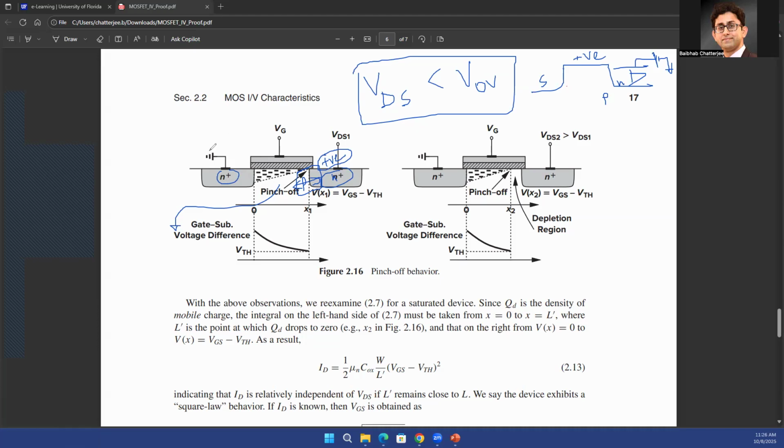That's a great point, that why does it have n plus in this diagram, and in the slides it has n. In terms of the physics, nothing changes, right? You still have electrons going from source to drain, the basic fundamental physics, nothing changes. The value of the current, the number of electrons that you can source, the number of electrons that are present in the drain, all of those things change, right? If you heavily dope it. And again, n plus or n, that's still qualitative. What matters is the quantity of the n doping, right? That can still be different, right, in different process nodes.